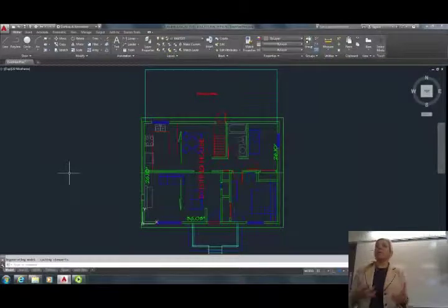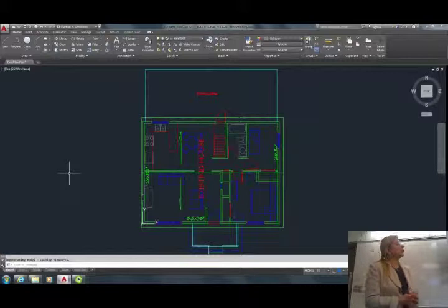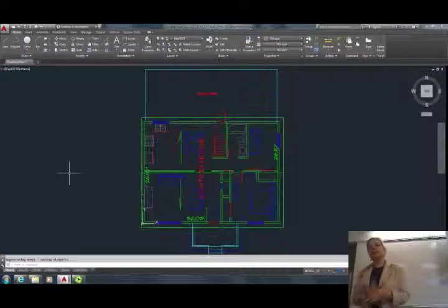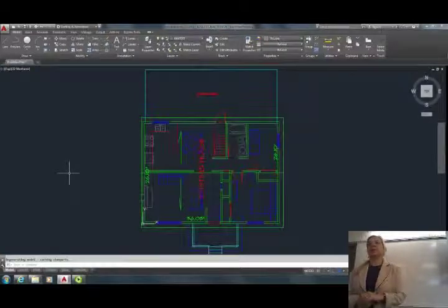Okay, so this is how I've been running our project for quite a while. So let's now introduce the concept of annotative notes. Annotative notes will change the size of the font. So you will tell AutoCAD what you want. So let's say you tell AutoCAD that you want 1/8 of an inch standard. And then you will be changing the scale that you will be printing at and the text will be always going up or down to remain 1/8 of an inch printed. That's the concept of annotative.